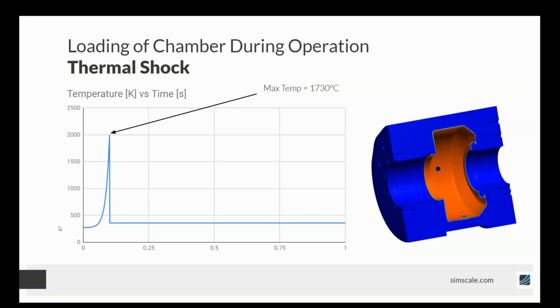We're going to see the increase of the temperature of the structure up to here, and then it's going to slowly descend. And this is what Explotechnik are interested in. They're interested in seeing how the temperature of the components is going to behave after the 0.1 seconds. So after the combustion, they want to see both how the temperature evolves over time and how the mechanical stresses also evolve over time.